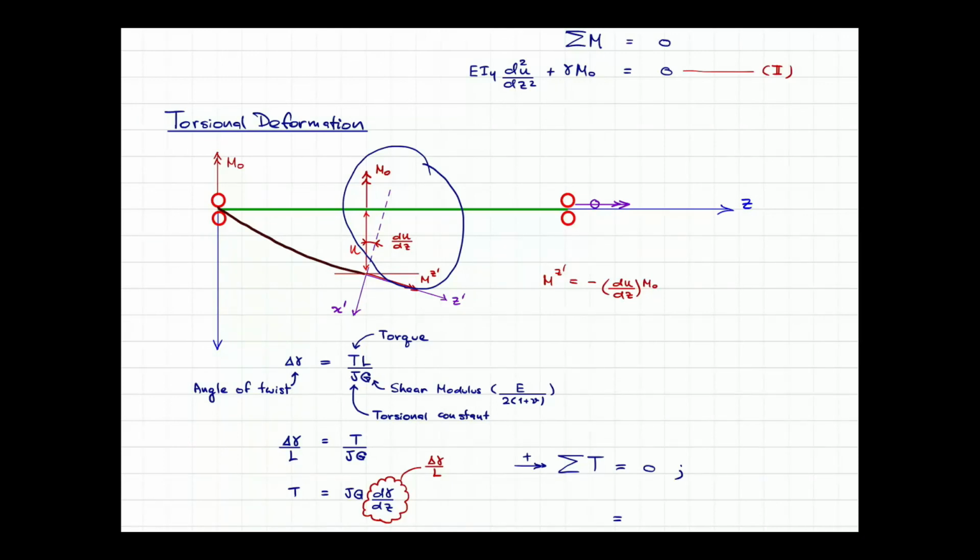If you cast the equilibrium on the undeformed configuration, you will not have this leakage because the M naught is perfectly perpendicular to the Z direction. But now, as we are talking about stability analysis, we cast everything based on the updated coordinate and axis. So the leakage from M, which is previously perpendicular to Z, can come into the Z prime.